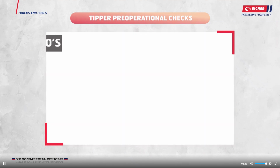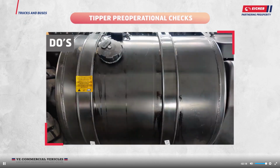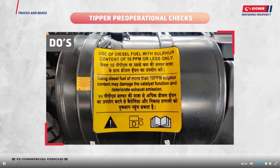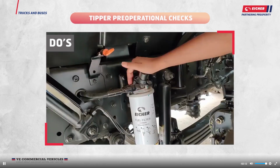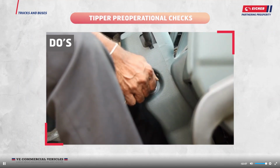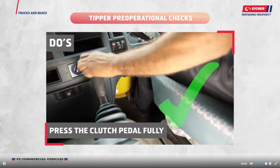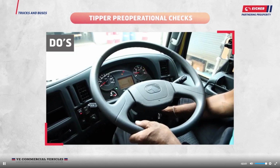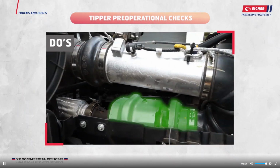Do's and don'ts. Do's: always use recommended fuel. Follow the caution sticker given on the tank. If the vehicle is not starting due to low fuel quantity, fill the fuel and perform the hand priming. While starting the vehicle or shifting the gears, always press the clutch pedal fully. After starting the vehicle, keep the engine in idle condition for 1 minute for better turbocharger lubrication and turbocharger life.